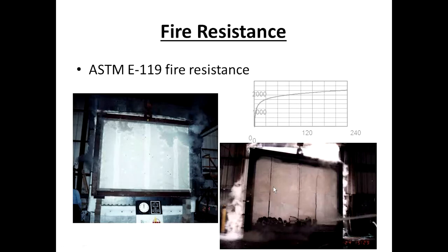And the second part of the equation that we're trying to solve is at this picture down here. You see a hose stream, that's this guy coming in here. That is not designed to see what happens when a fireman's hose hit it, but in effect it's designed to show what happens if something structural, let's say I have a joist coming across the top of that wall, it fails and it falls into my wall. Will it fail my wall? Yes, it has something to do with the cooling and eroding effect of the water, but not the fireman's hose.